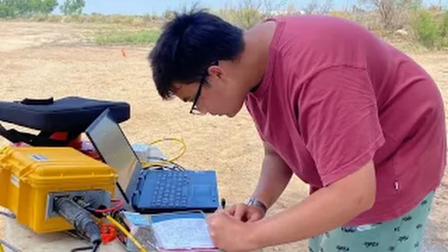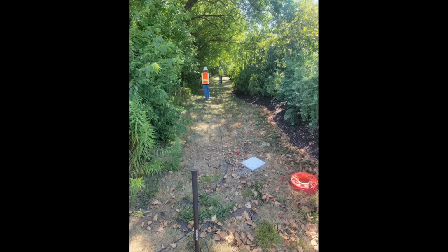And the other aspect that we employed to optimize pile lengths was employing geophysics. We did a series of case studies throughout Kansas in 2022 where we went back to jobs that had been built already, where we had previously done the pile testing, and did surface geophysics to see if there were indications of a certain compression wave velocity where the piles ended up being driven to.